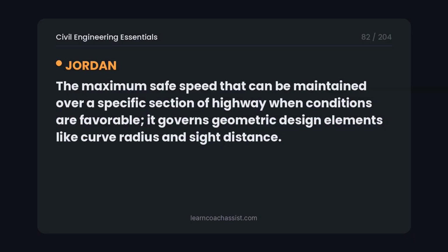What is the design speed of a highway? The maximum safe speed that can be maintained over a specific section of highway when conditions are favorable. It governs geometric design elements like curve radius and sight distance.